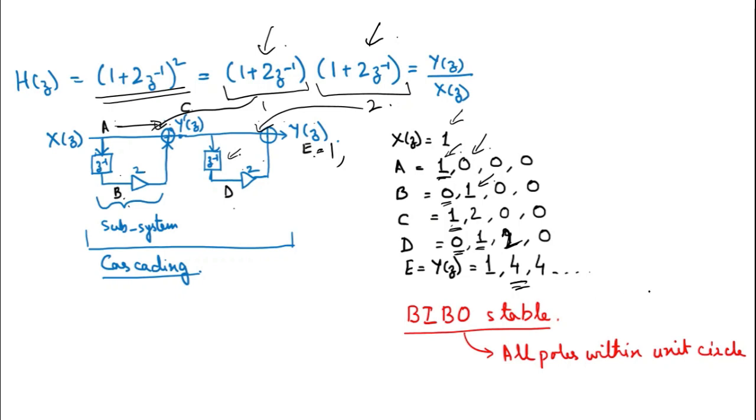In the next instance, at C we are having the value of 2. So at D, it got stored in the delay. So at D we will be having the 2. 2 multiplied by 2, 4. It will be 4 over here. However, in the previous cases, directly from the input there is nothing, 0. So 4 plus 0, so you get again 4.